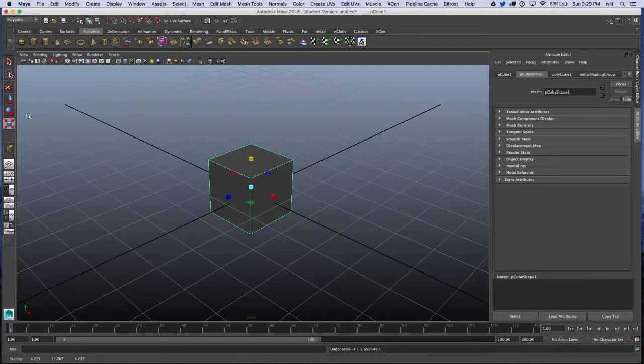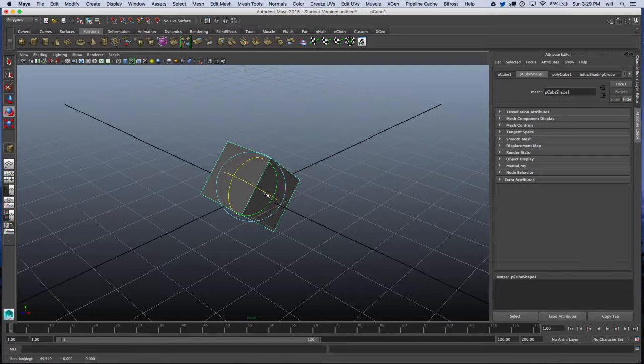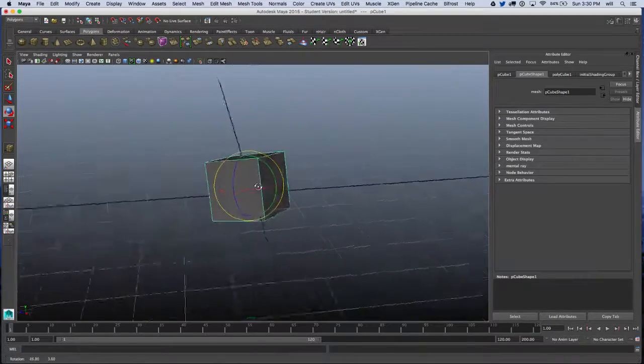Another tool that we didn't go over yet is the Rotate tool. Click on that. You can rotate these this way, rotate them that way, or you can rotate them in any way you're looking at it. This is the flat 2D plane rotation tool. So any way you're looking at it. Now, if you want to curve and turn around this, you can hold the Option key and twist and drag.